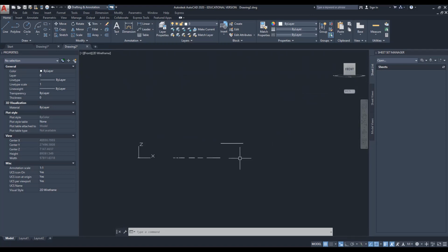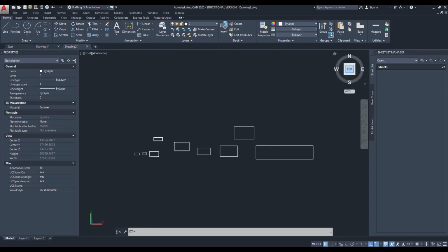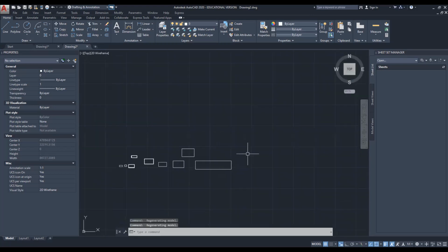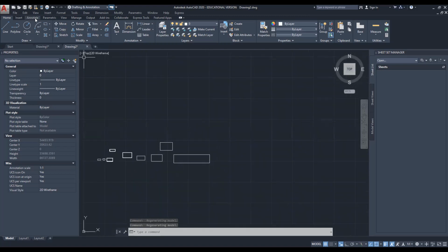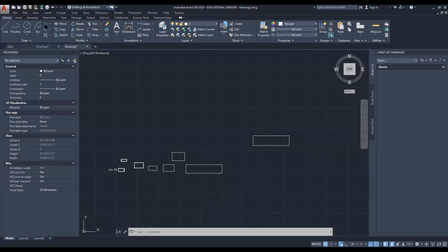So for creating rectangles at different elevations, we can create this type of rectangle by selecting the elevation sub option. The last sub option in rectangle is thickness. Using thickness, you can give a thickness value to the sides of the rectangle. I'm going to give a thickness of 300 units, giving enter.